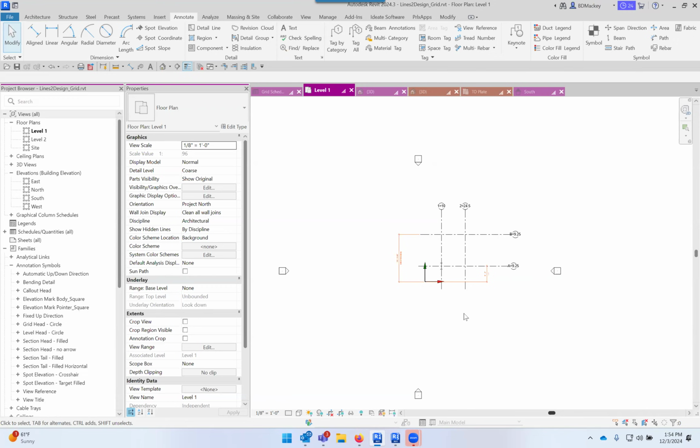Tim wonders if AutoCAD does a better conversion since it supports import out of the box. AutoCAD, I believe it used to create its own text style as well, which drove me crazy as well, because you could do a smart table. No, because with AutoCAD, if you did it as a smart table, it would actually bring in the data from Excel. Because they call it a smart table, but you're just putting fields in. So it literally wasn't looking at the size of the text or the width of the columns. It's just saying, hey, grab this data and bring this data across and use this table style to do it.